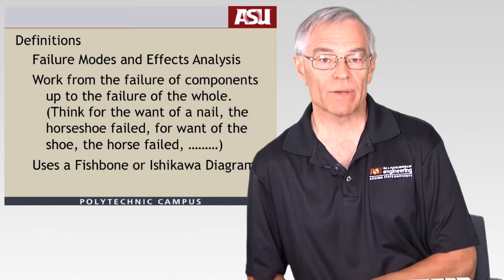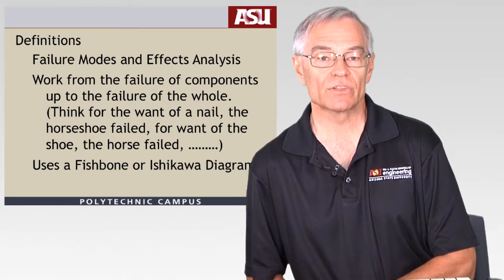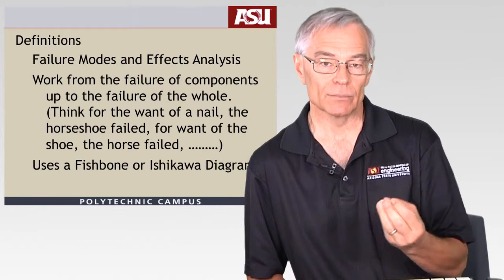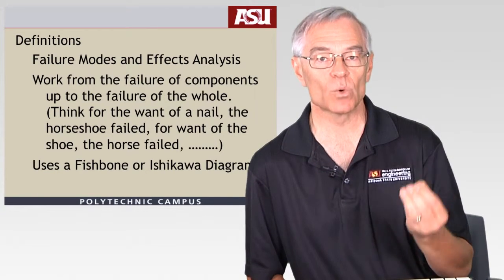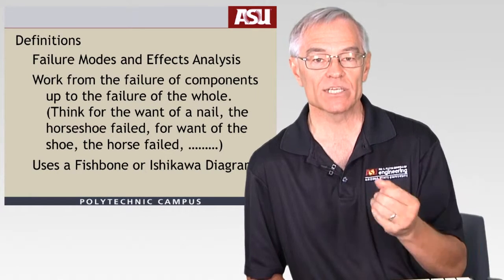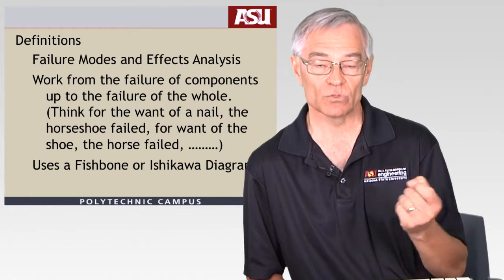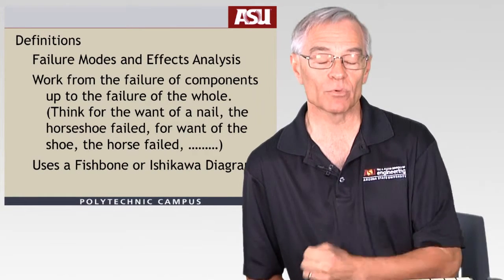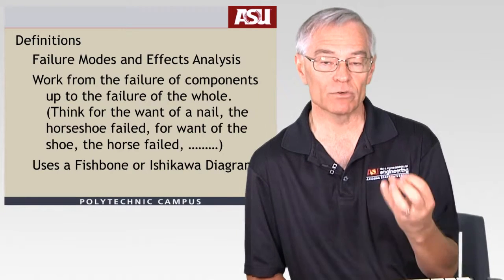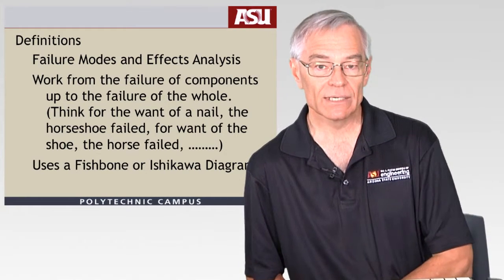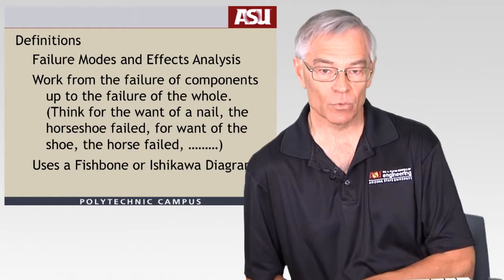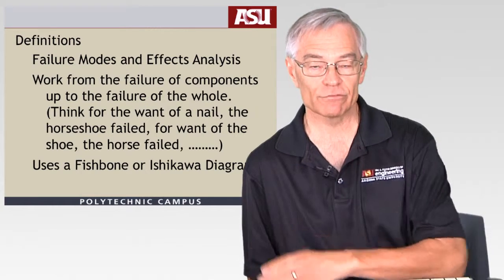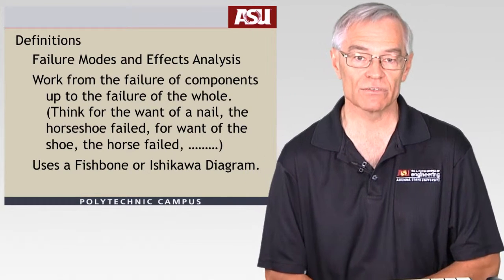So you always want to think about failure modes and then the effect. So you think about not just components, but all the way up to the system. So a specific component might fail. What is that going to do to the system? And that's typically what you may think about in the HAZOP as well, where an operability or a process operation may be impacted by a valve or some component failing. Think nuclear plants, for instance, where one piece of the overall process goes down. It could cause a cascading effect of problems that lead to a very unsafe situation.